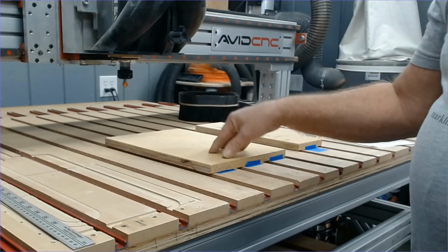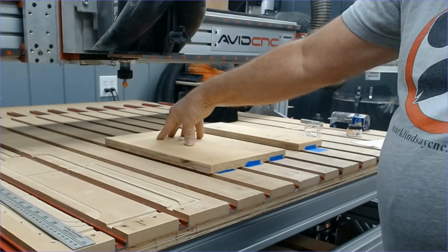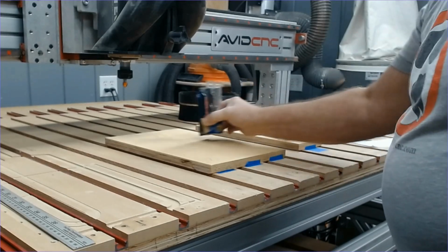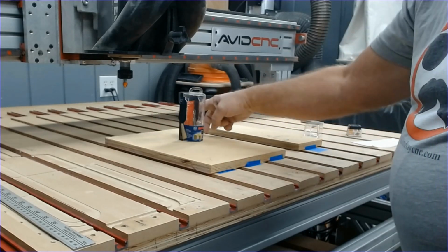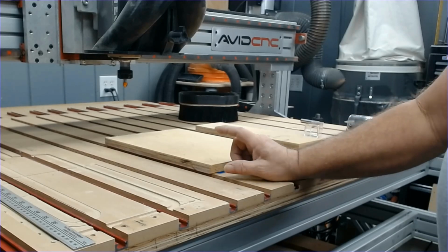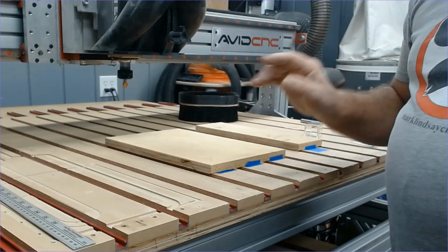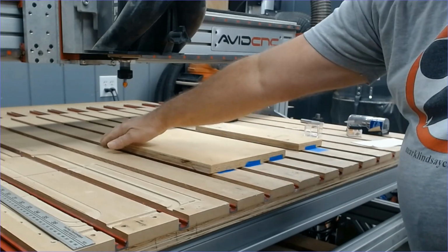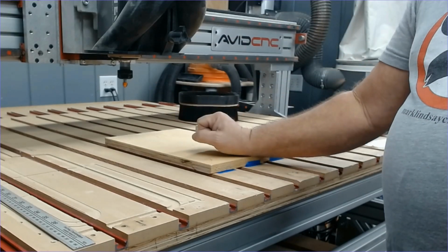If I have to do a bit change, if I V-carve the top of this material, then take out my V-bit and put in my end mill to do the profile cutout, I will not reset the XY0. No matter where I have set my XY0, be it the middle or one of the corners. I will only reset my Z0.